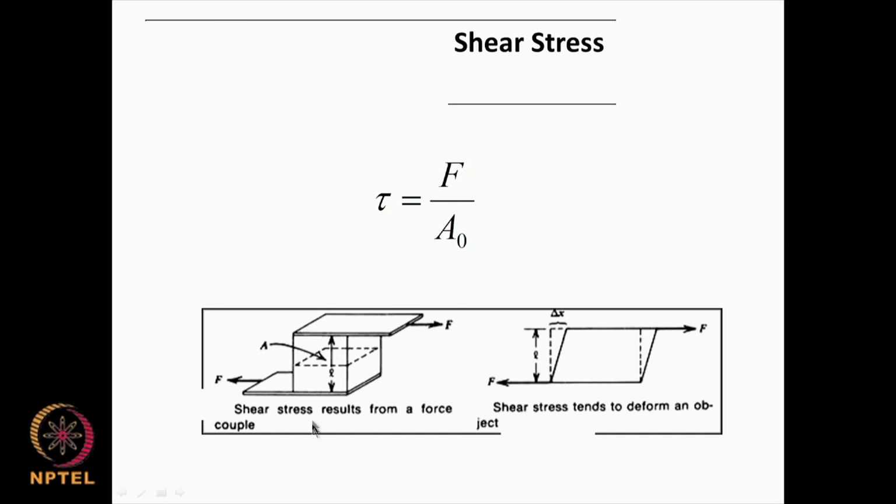Suppose I have a lower jaw with lower teeth and an upper jaw with upper teeth. When they come in contact with each other, they do not meet exactly, because there could be a slight displacement in the jaws, so there will always be a possibility of shear forces acting on the teeth. When there is a shear force parallel to the surface, there could be a small displacement called delta x, and this could be the length. So the shear strain could be delta x by L.